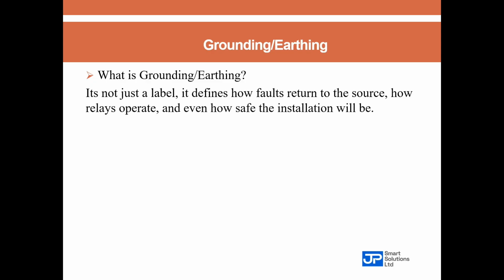It defines how faults return to the source. It defines how our protective relays operate. It also defines how safe our electrical installation will be. Not just a label. I will illustrate that using ETAP software.